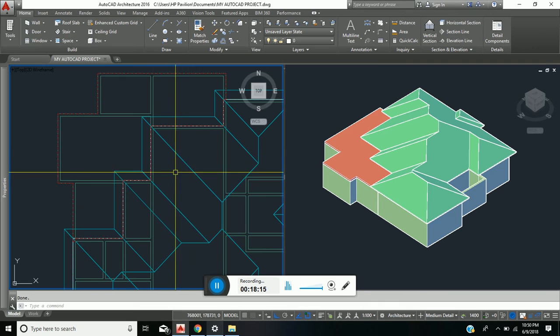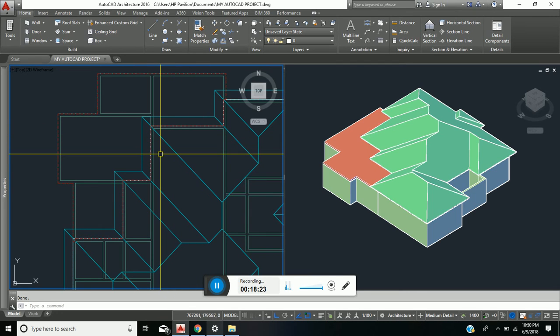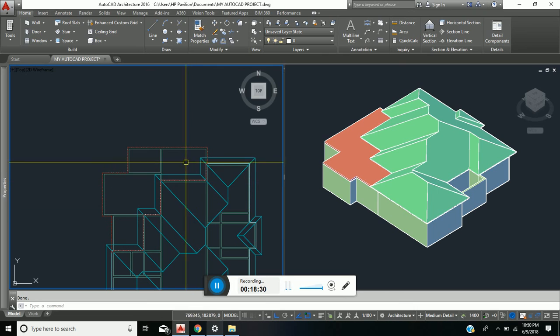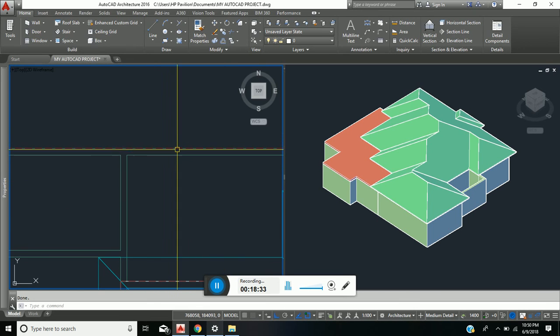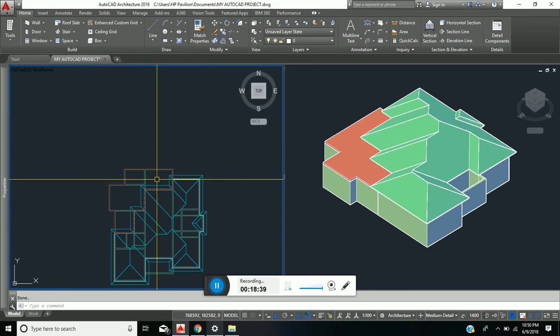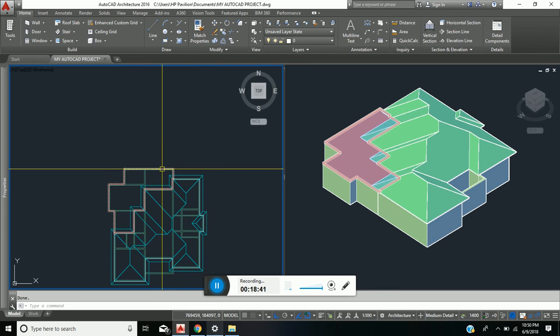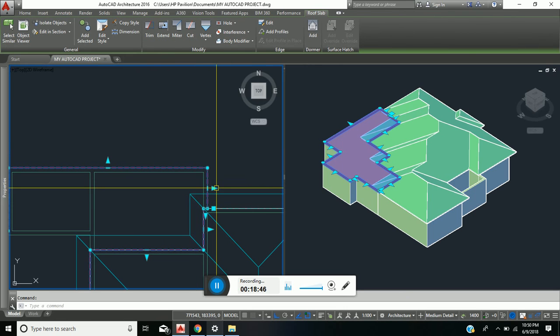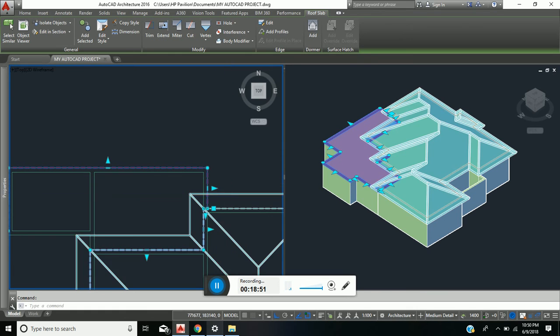So from the living room, for example, or from the dining room, looking up, you'd be seeing a portion of the slab around the building here, because it would have had an overhang which would have protruded into the living room. And so we gave it an overhang of 0. What we're basically going to be doing though is to manually put that overhang on the sides where overhang is required. To do that, you select the slab, and you would now have grips that you could grab and pull in the direction you wish those overhangs to be.